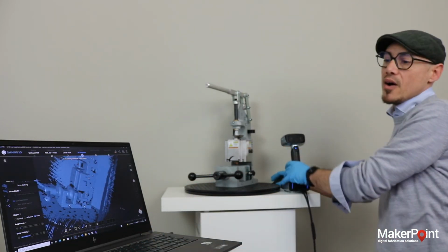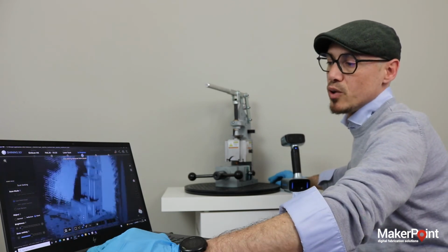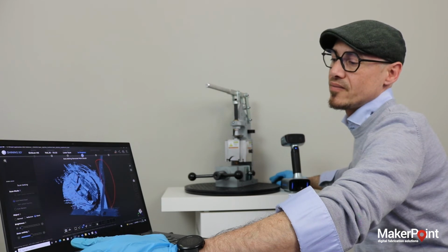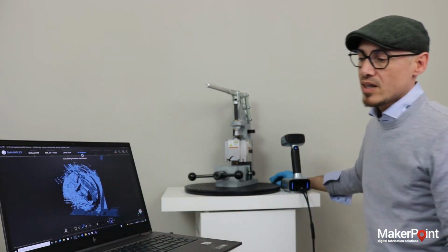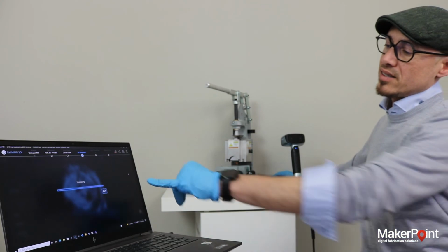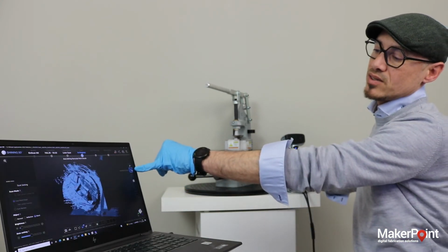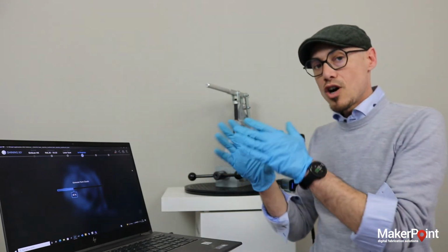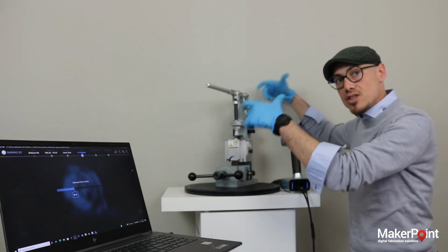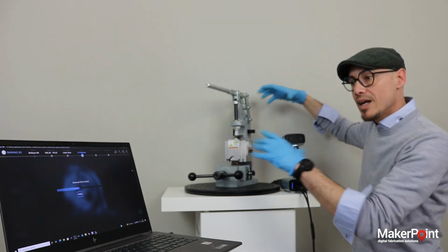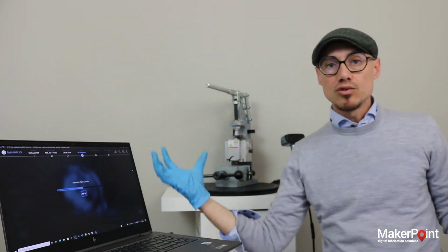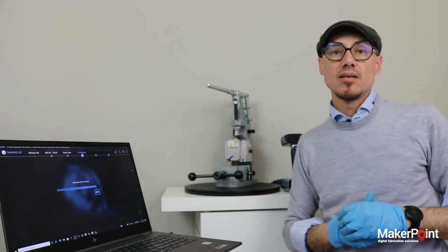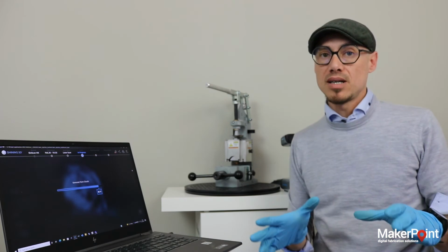You can now cut and remove the parts that you don't want to keep, such as the wall in the back. And then accept and click the squarish button to generate the point cloud. Once you generate the point cloud, your job is simply done. Change position of the model and scan again. The software is going to merge the 2 point clouds together and extract a watertight mesh automatically.